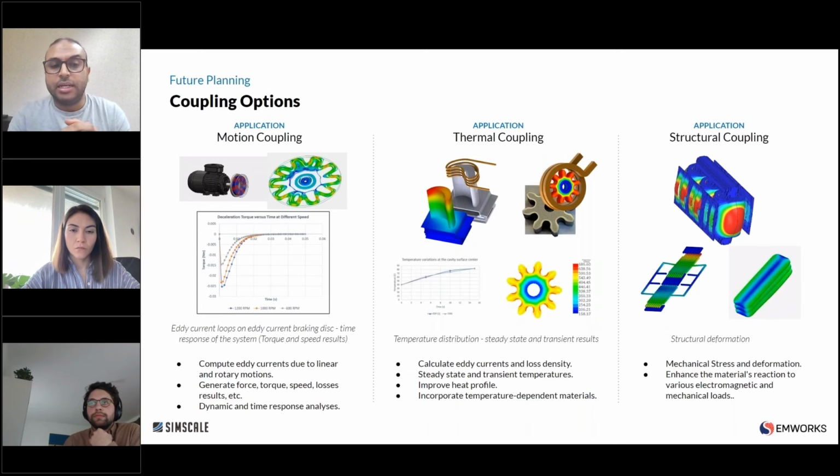So this is an electrodynamic simulation that can be used for a wide range of applications like motors, eddy current braking, couplers, solenoids, and so on. It's a mechanical coupling simulation and can be used for steady state motion. So you just apply a constant speed, or you apply some dynamic speed that varies versus time. So you can use the force and torque to generate the time response due to that force and torque.